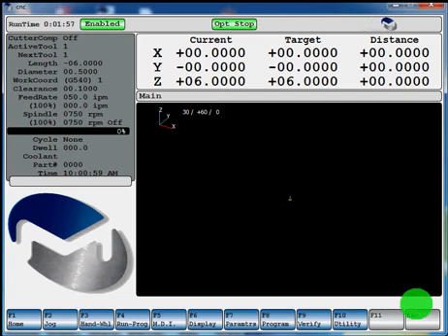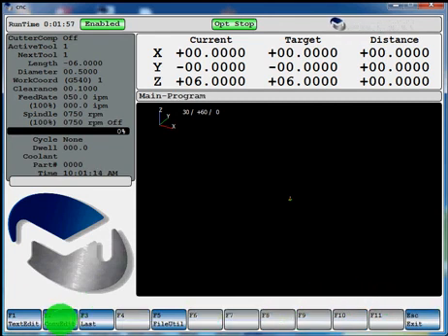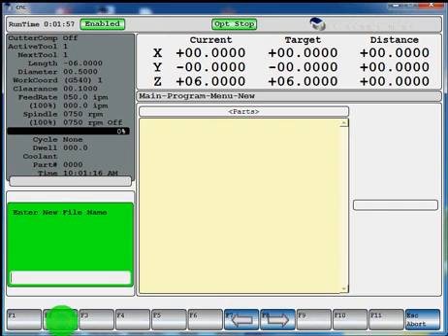This video will show a demonstration on your Milltronics 8200B control. We're going to be setting it up and milling a frame and milling a pocket. So the first thing you're going to want to do is press F8 Program, F2 Conversational Edit, F2 New.